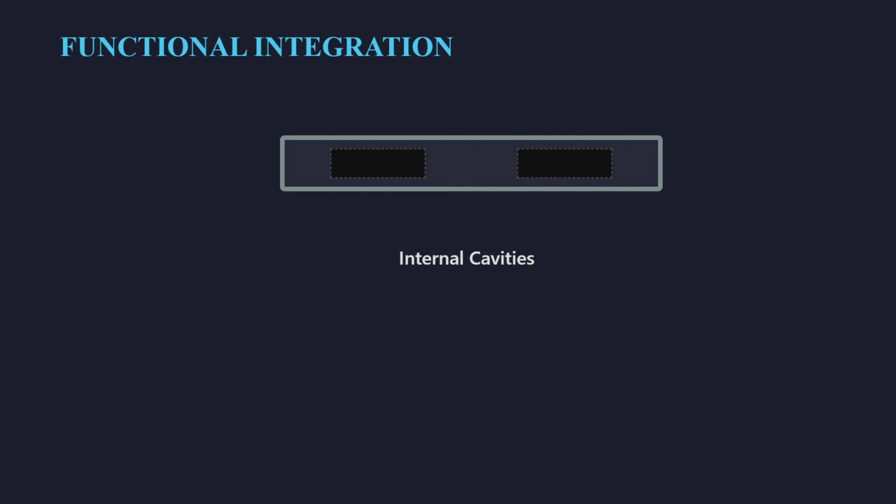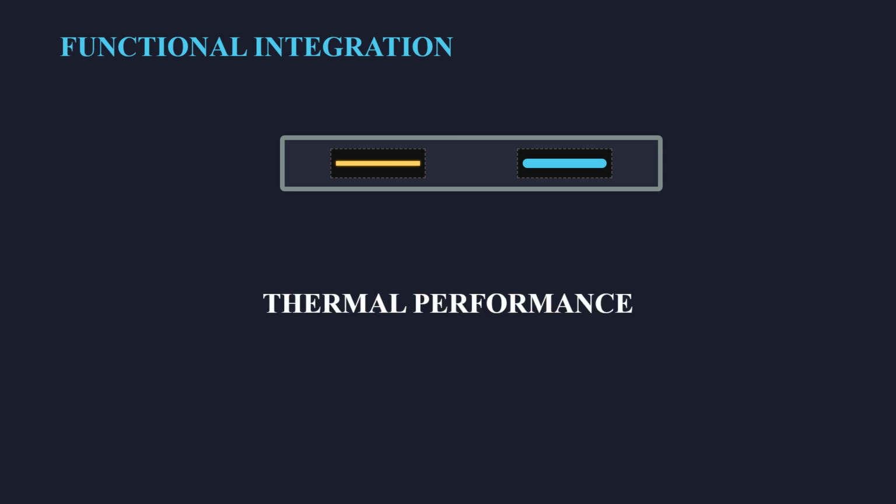Three-dimensional printed walls are typically designed with internal cavities, serving dual purposes: reducing material consumption and accommodating utilities. Electrical conduits and plumbing lines are routed through these voids during or immediately after printing, minimizing post-construction cutting. Thermal performance requires the integration of insulation materials to meet energy efficiency codes. This is achieved either by injecting lightweight materials like foam or perlite aggregate into the cavities post-printing.